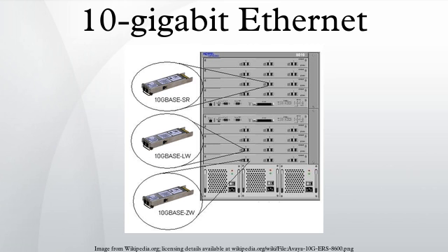To ensure that specifications are met over FDDI grade, OM1 and OM2 fibers, the transmitter should be coupled through a mode conditioning patch cord. No mode conditioning patch cord is required for applications over OM3 or OM4. Some 10GBASE-LRM transceivers also allow distances up to 300 meters on standard single-mode fiber, however this is not part of the IEEE or MSA specification. 10GBASE-LRM uses electronic dispersion compensation for receiver equalization.